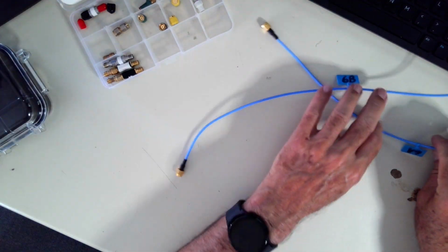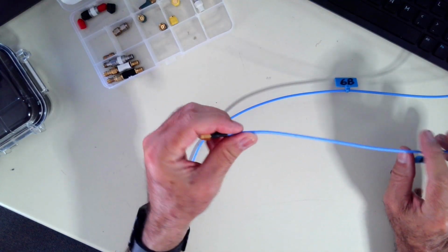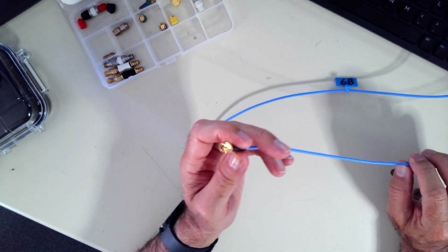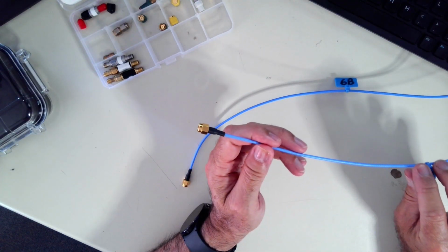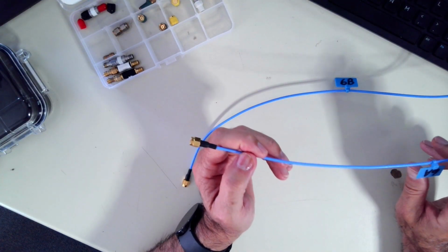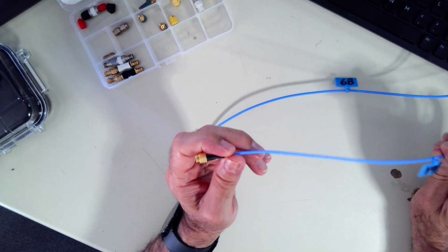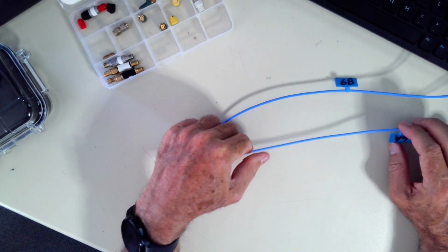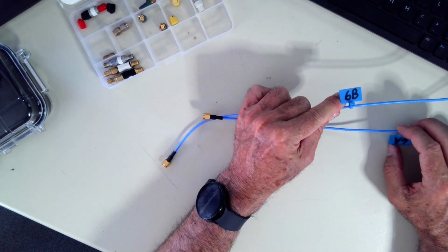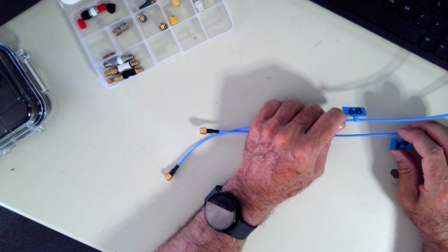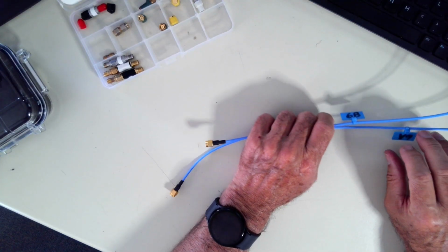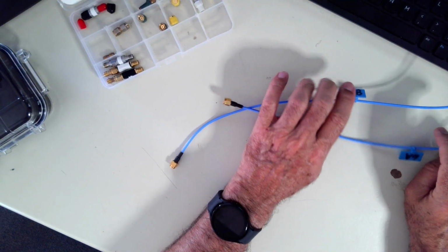Our test cables that we have here are 20 inches long, and these are in our benches. They're made from RG316D. They have a max useful frequency of 6 gigahertz. By coincidence, I am at bench 6, which is why you see a 6A on this label and a 6B over here on this label. This just tells you I'm working at bench 6, and these cables belong to bench 6, so that when they're done, you need to put them back in the resource drawer for bench 6.